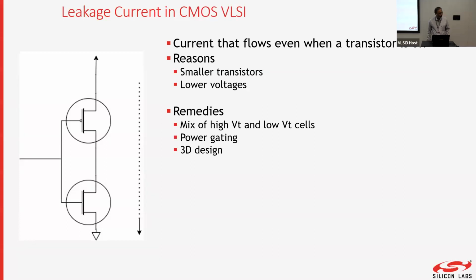Now, the VT and the supply voltages are related. So that has a cost in terms of power consumption. If you're doing a lot of switching, then you might as well use higher voltage. If part of the circuit is asleep for a very long time, you tend to reduce the leakage of that. So you have to make an intelligent choice.